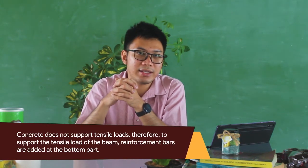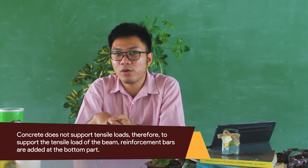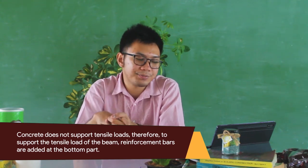But concrete again is only good in supporting compressive loads, but it is very bad in supporting tensile loads. So that is why concrete beams are usually reinforced with reinforcement bars, or your rebar or your steel bars.